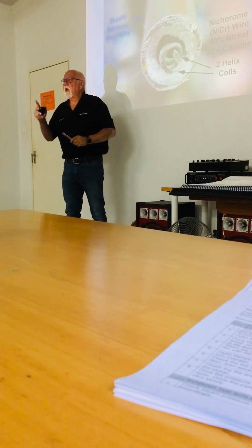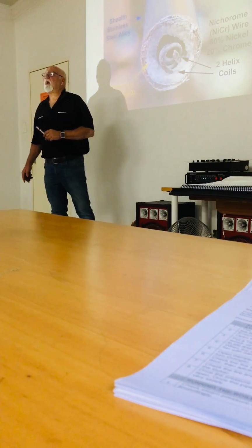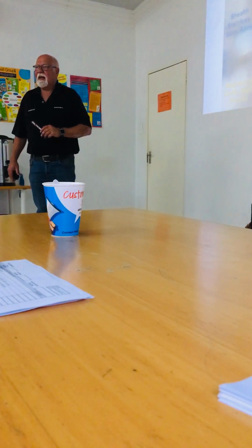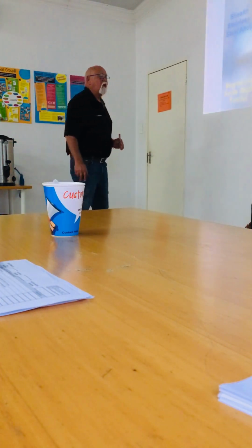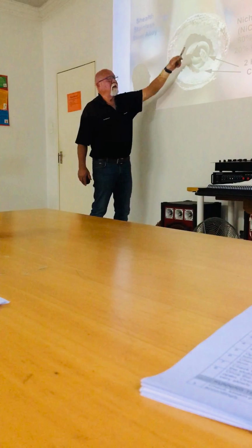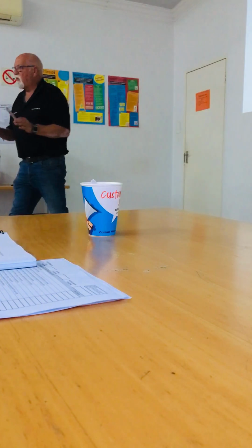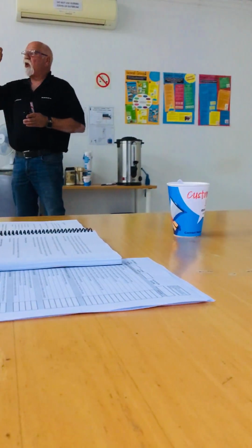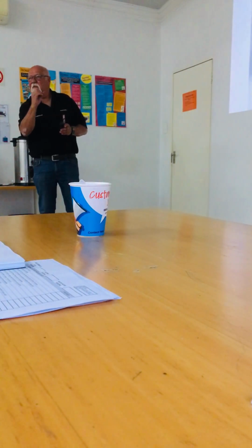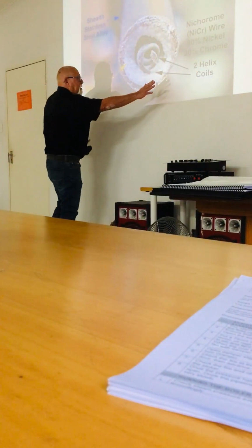What does that do? When I apply electricity and electricity flows through this coil, it becomes incredibly hot. You can't touch it, it'll burn you to pieces. It builds up an enormous temperature. This magnesium oxide powder, this white powder here, just ignore that. The only reason why that powder is there in an electrical element is so that we can keep that electric coil in the middle roughly. We don't want it to lie on the bottom of it. That magnesium oxide powder does absolutely nothing for us here.